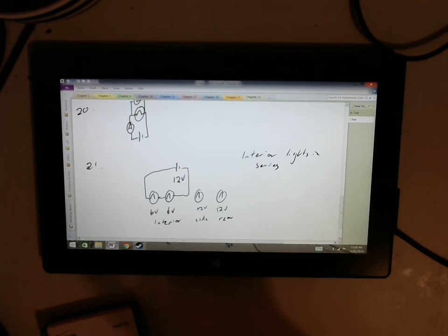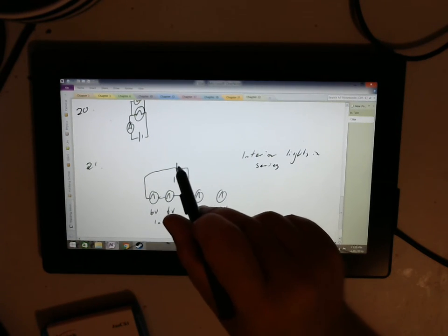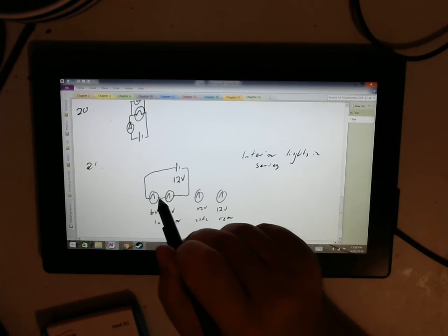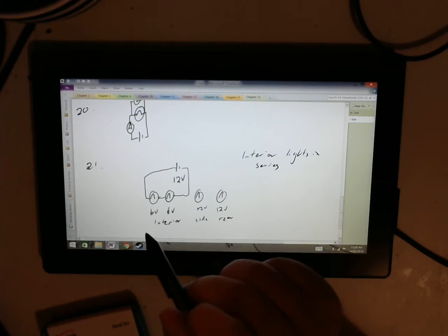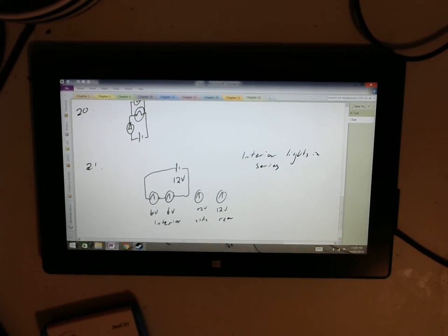Now this is a 1-star question. There's no complexity to this. It should be reasonably just a straightforward recognition, description, or identification type question. We've identified here that we've got 2 6-volt bulbs. If we're giving it 12 volts, they need to be in series. If we had set these 2 up in parallel, they'd both be getting 12 volts, even though they're only said they can handle 6.